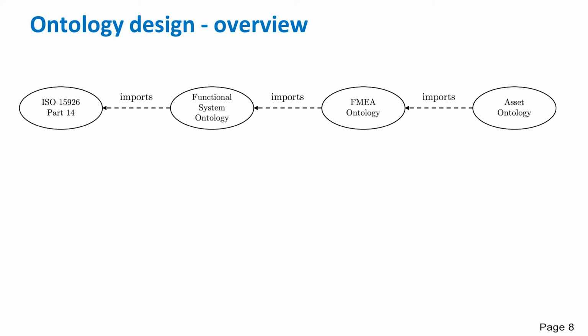This will typically draw on a variety of industry standards. Next, for the FMEA ontology, we add the terminology of failure modes. The ISO 14224 standard for reliability and maintenance is a primary source for this vocabulary. Armed with the generic vocabulary, we are ready to map the spreadsheets that describe the specific individual asset under consideration into facts in the ontology language, its composition into functional units, as well as the ways these units may be expected to fail during operation, as uncovered by the FMEA analysis.